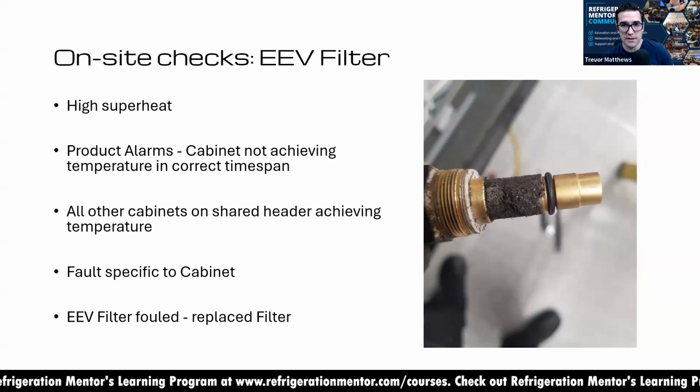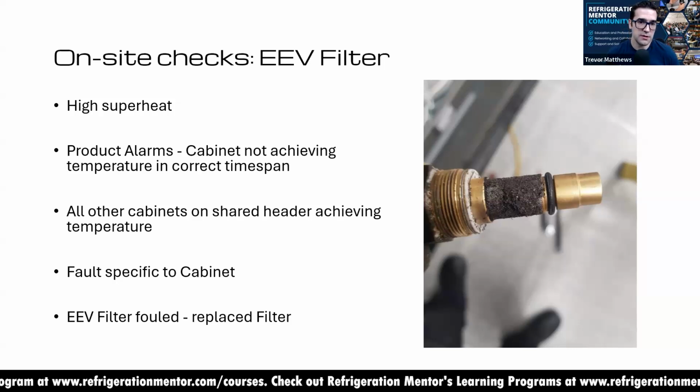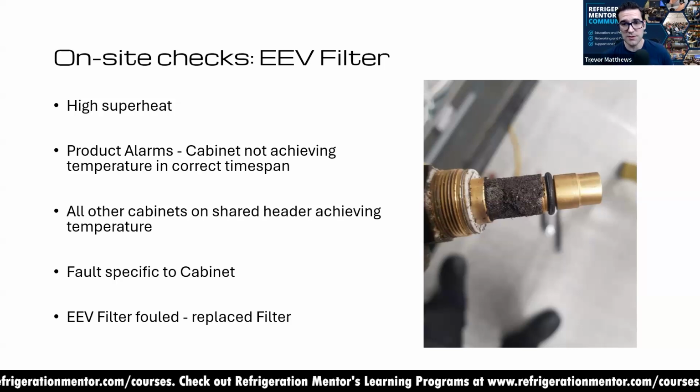Think about 410. If you use a reclaimer for 410, low temp or subcritical CO2 is still the same pressure. So look into that with the manufacturer of that equipment, because I know lots of technicians using reclaimers for CO2 vapor that's below the pressure threshold.